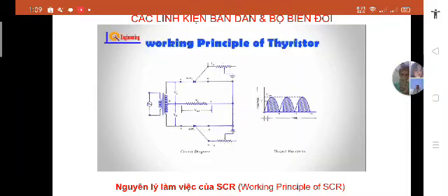In operation, the thyristor or SCR will not conduct initially. It requires a certain level of current to flow in the gate to fire it. Once fired, the thyristor will remain in conduction until the voltage across the anode and cathode is removed. This obviously happens at the end of the half cycle over which the thyristor conducts. The next half cycle will be blocked as a result of the rectifier action. It will then require current in the gate circuit to fire the SCR again.